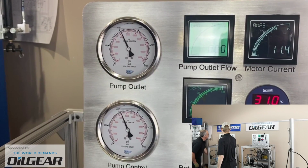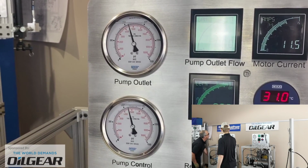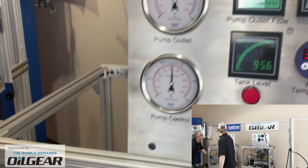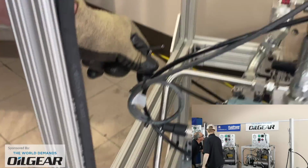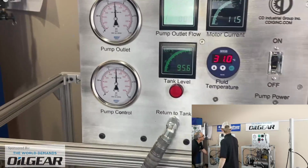Make very careful adjustments. In this case, to go from 600 to 750 was only about 1/8 of a turn. It's a very small amount of turn on this key to move 150 psi. About 1/4 of a turn was 300 psi change on this particular adjustment. This is a Nachi America pump. You'll see the data sheet for.